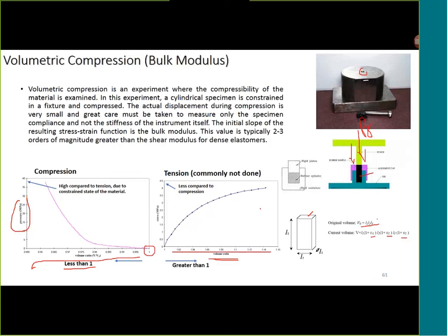Look at that. Again, when you are compressing the rubber in a constrained space, the amount of pressure required to make even a small change in volume is really high. But when we are stretching a rubber in an unconstrained space, though it is unconstrained in the box, as it stretches, the volume is going to shrink. So this rigid wall cannot offer any boundary. As the material is going to shrink, it can stretch. So to make even a large volume change, the pressure required is very little, which is negligible.